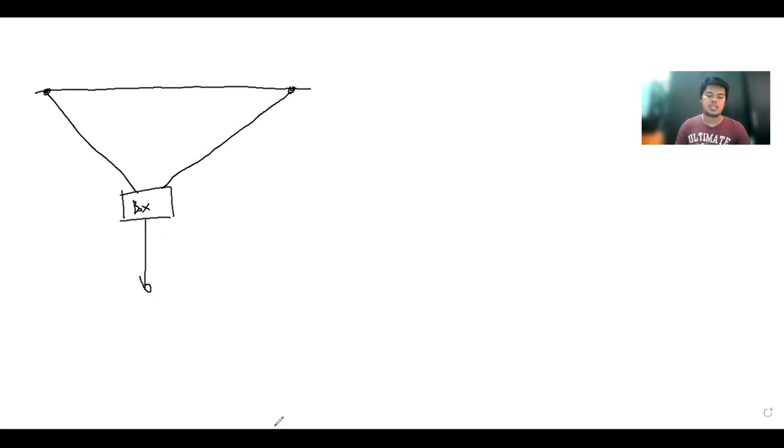The weight of the box is given to be 50 pounds. The ropes make angles of 30 degrees and 60 degrees, and it doesn't matter which one is 60 or which one is 30. The question is asking for the biggest tension of the rope. Since the ropes experience stretching because of the weight, we may consider that rope 1 experiences tension T1, and rope 2 experiences tension T2.